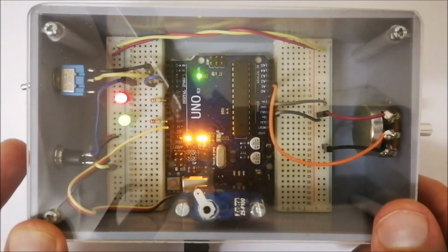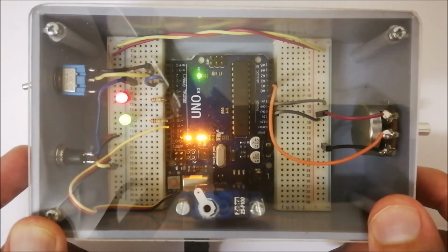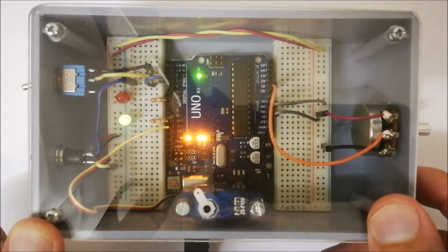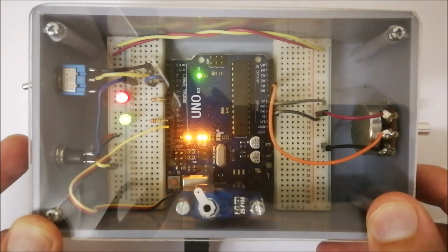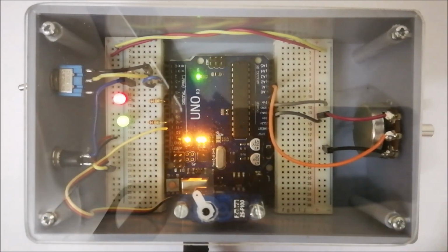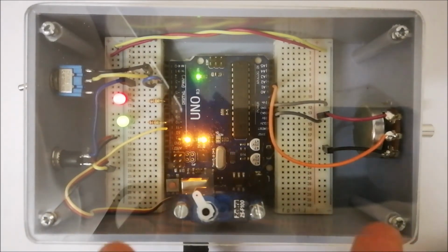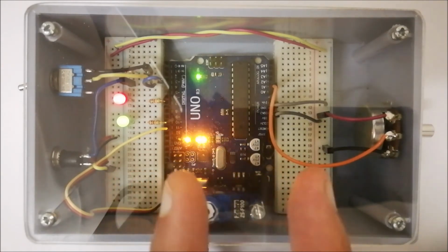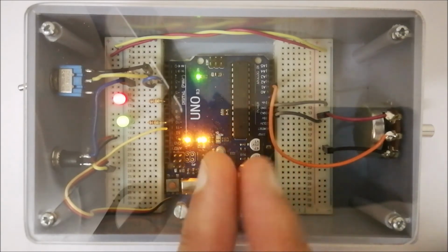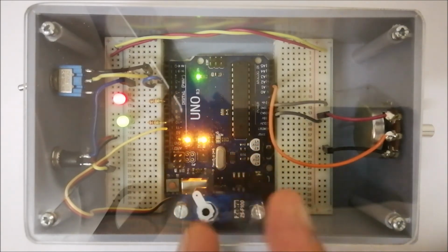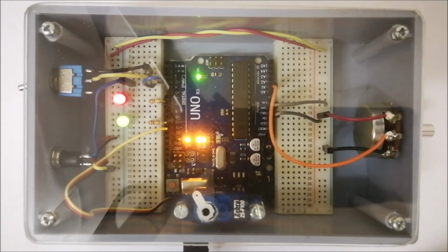Now when I activate a pull down resistor, if I push the button once, it switches off. If I push it again, it comes on again. Okay, now you'll notice that there are times that I push it and it will stay in the same state. That could be because, if you look at the switch inside, there are two metal plates touching each other. We think it's only touching once, but as a matter of fact, it's almost like clapping against each other inside. And that's the reason it sometimes stays in the same state.